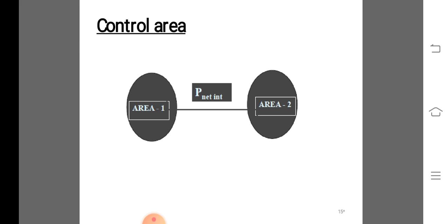The frequency will be less than normal at the end of the governor response period. The load increment will be supplied partially by A and partially by B. The tie line power flow will change thereby.